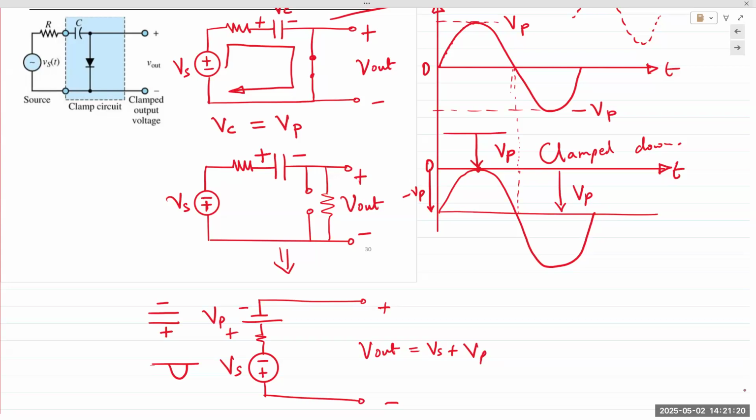So your capacitor is connected like this, right? So if you now have a resistor, the capacitor has a pathway to discharge. The reason the capacitor is not discharging is because the diode is as good as an open circuit. A real life diode obviously has very high resistance. The capacitor will discharge, but it'll be like microvolts perhaps, so small that we could not even measure it. So for all intents and purposes, the capacitor is not discharging through the diode. So if you have a load resistor, then we have to design the circuit in a way that the capacitor does not discharge a whole bunch through that load resistor. Does that make sense to everyone?